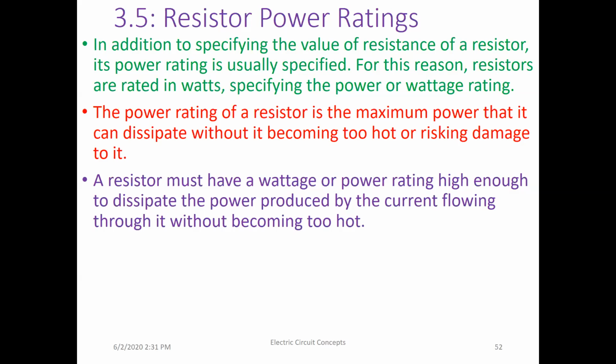This is what we call the rating voltage. Or when you buy a machine of 1000 watt rating, that means this machine can produce 1000 watts, not more than that. That machine requires a 120 volt rating; we cannot apply more than 120 volts, otherwise this machine or device will be damaged. So this is the meaning of the rating.